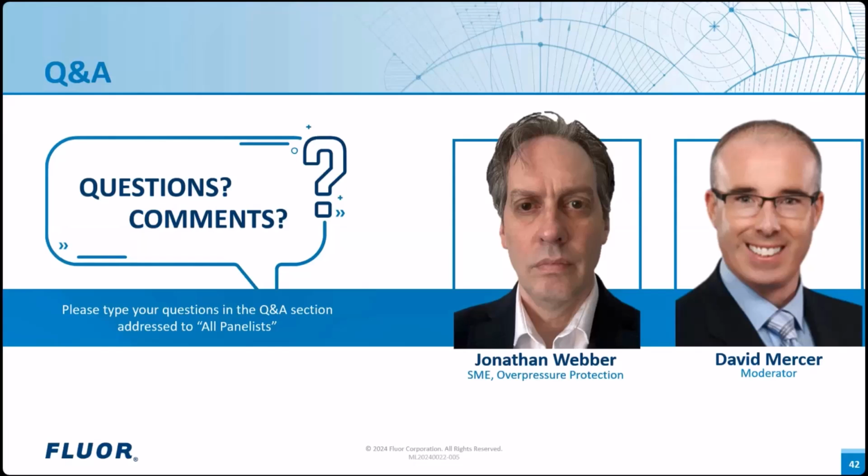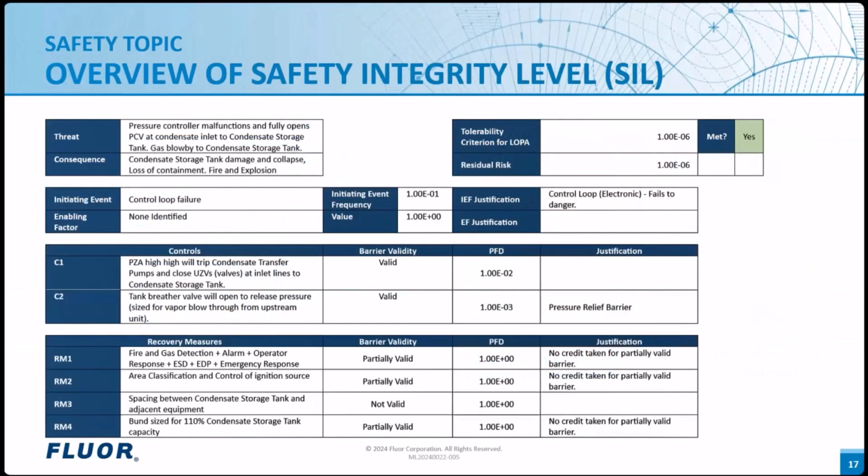To clarify that point, PFD is a probability and it is not expressed in years. During the safety topic, years were mentioned, but it was not used as the unit of measure for PFD. It was actually used as the measure for risk or likelihood.